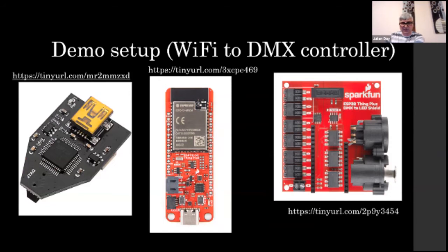But crucially, I don't know if you can see there, it's got a little JTAG header, which is actually compatible with the ARM style headers. So you could solder in your 1.27mm pitch header and plug this JTAG adapter straight onto it, and you wouldn't need a third-party board in the middle.